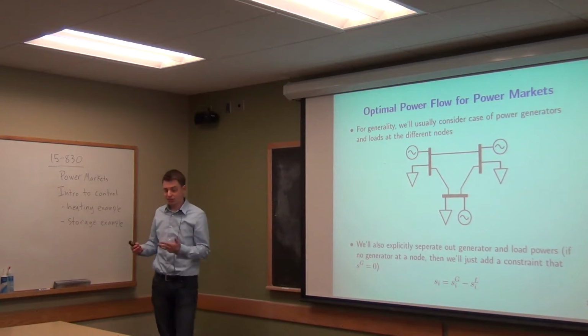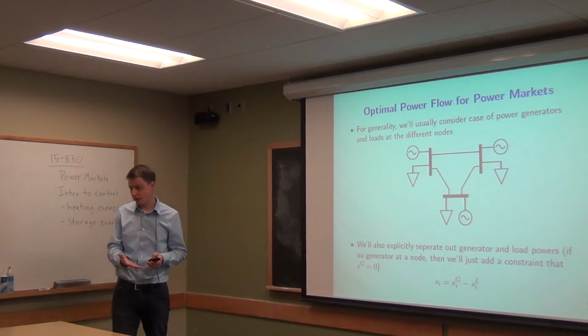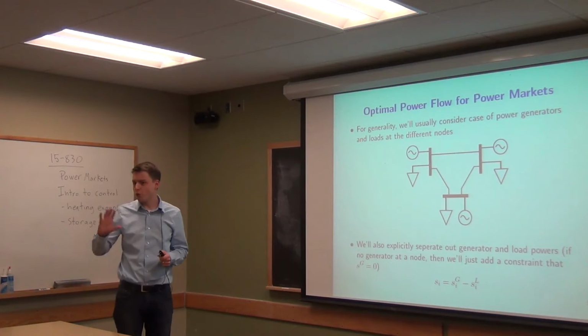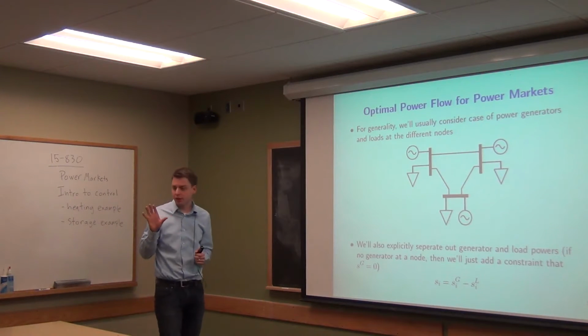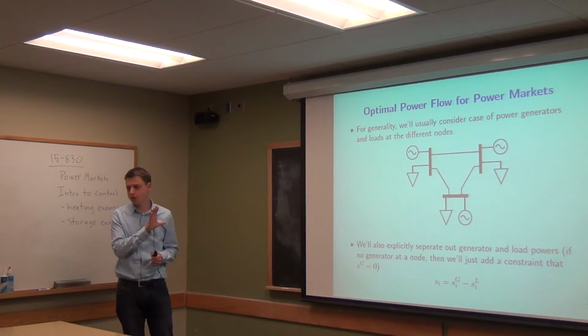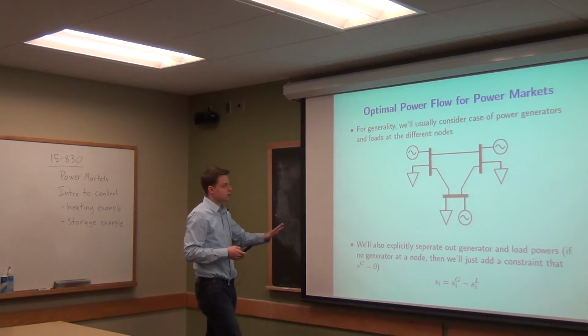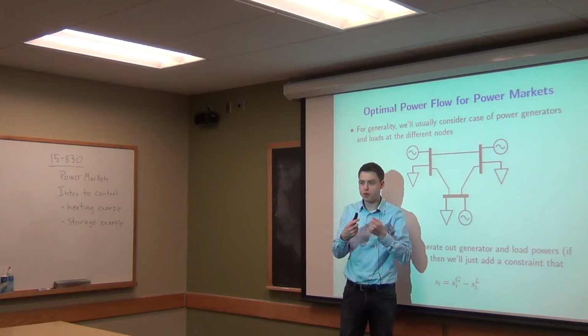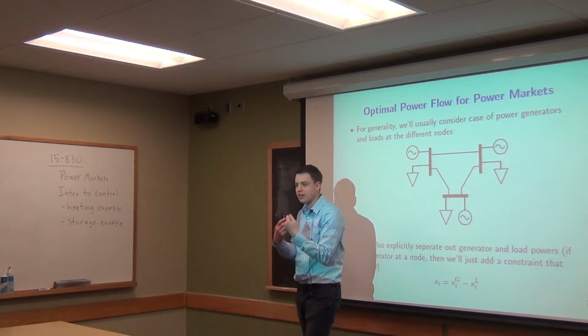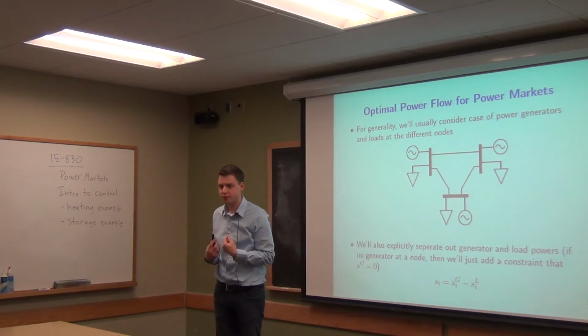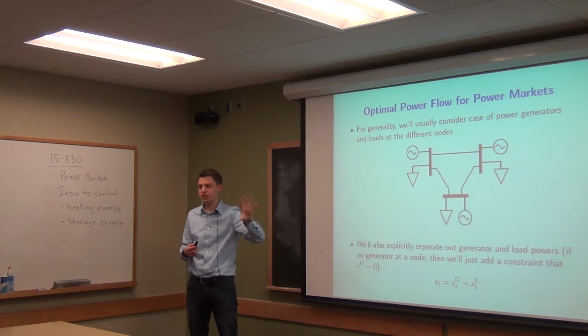And this will be handy because there are some nodes that have both generators and loads. And actually, more importantly than that, for computing things like prices at each node, you really want to be able to talk about what's the price for generating more energy in terms of if that node consumed more energy. So you want to have the ability to have loads at each node.